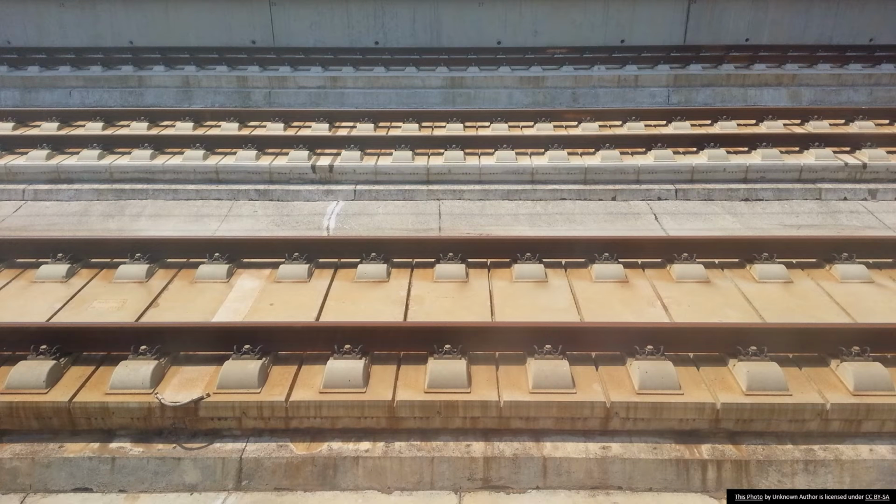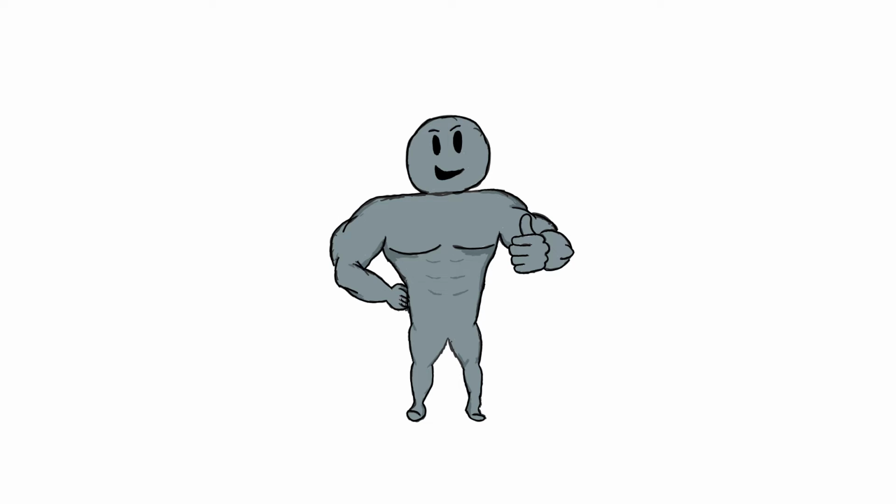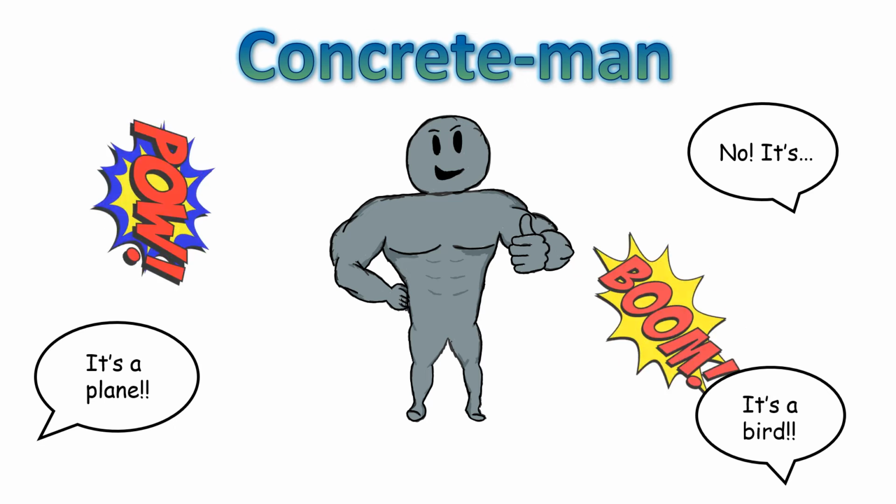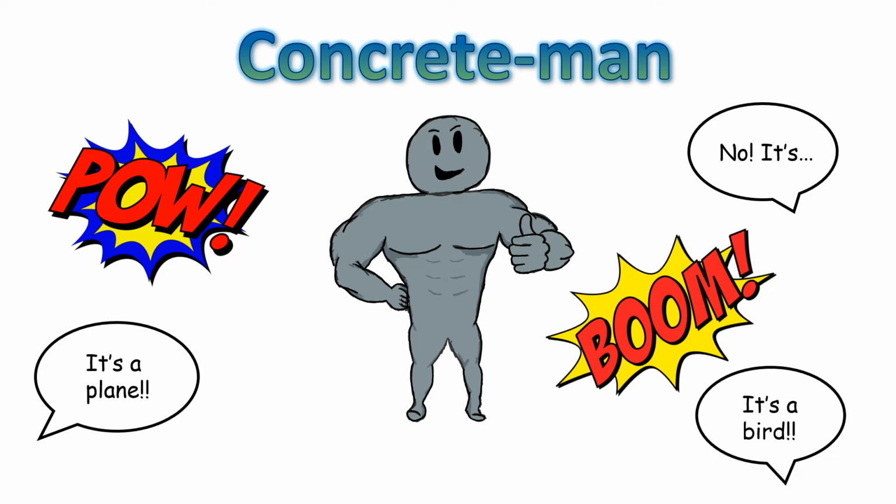Even though ballast tracks serve as a fairly solid foundation, they aren't the only foundations being used today. Many countries use ballastless foundations. This type of track replaces the ballast with something like concrete. The concrete can give a much smoother ride and results in less vibrations. Concrete is an extremely useful material for large-scale projects because of its impressive capability to resist compressive forces.